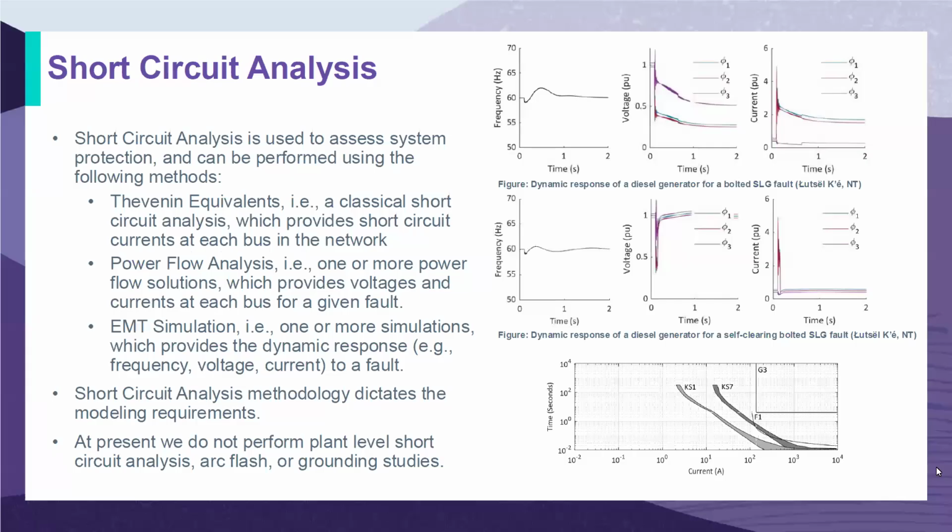And protection is somewhat of an art, somewhat of a science. We don't do the protection design, but we could do the protection analysis of the different faults: line-to-line-to-line, line-to-line, line-to-ground, line-to-line-to-ground, line-to-line-to-line-to-ground. What are the fault magnitudes? And will the protection system operate as it should? As in, does it stay online when it should stay online? Does it disconnect when it's supposed to disconnect?